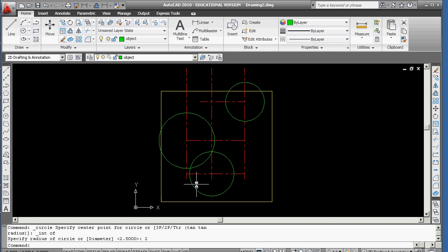I'm going to put the radius in here and the radius in there by doing some breaks. BREAK, you break in a positive way. And now the fact that this is a fillet from the outside to outside, we'll see how that works, because these curves are kind of odd. So tangent radius will definitely work.